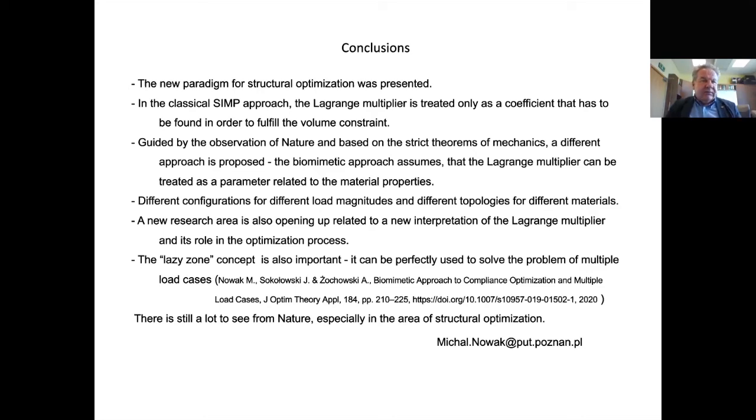For other materials used in mechanical design, we have to find these values. I think it could be similar to von Mises stress, something characteristic for the material. So maybe this Lagrange multiplier could also be put in the tables, and for each material we can choose the value of this Lagrange multiplier and start the optimization with this value as an assumption instead of a volume constraint.